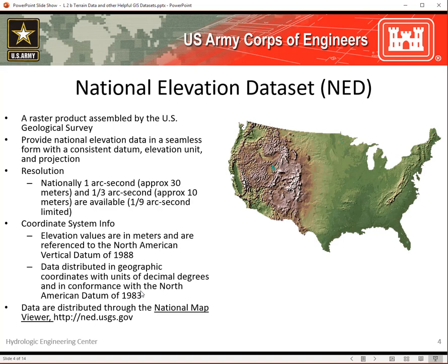All right, so let's talk more about terrain data. For the United States, you're going to go to the USGS website and download the National Elevation Dataset terrain data. You have different options from this website. You can choose 30-meter terrain data, 10-meter terrain data, or even smaller 3 to 5 meter terrain data. One thing to note, or a couple of things to note when you gather this terrain data from the USGS, and here's the link at the bottom for navigating to their National Map viewer, which allows you to identify the location and the extents of the terrain data that you want to download.